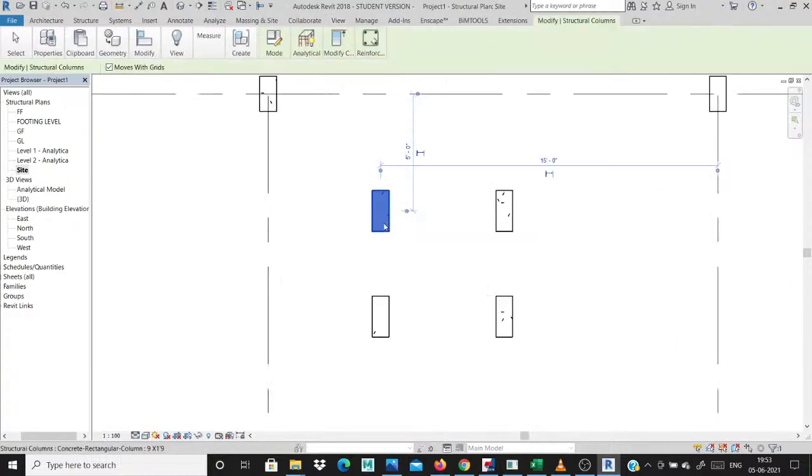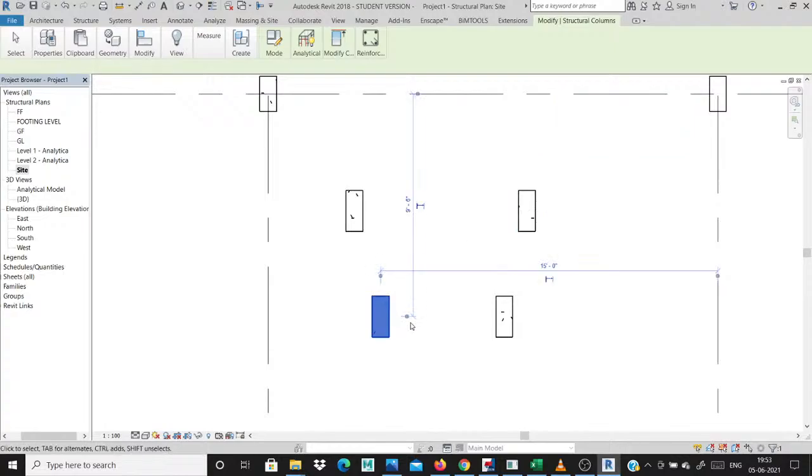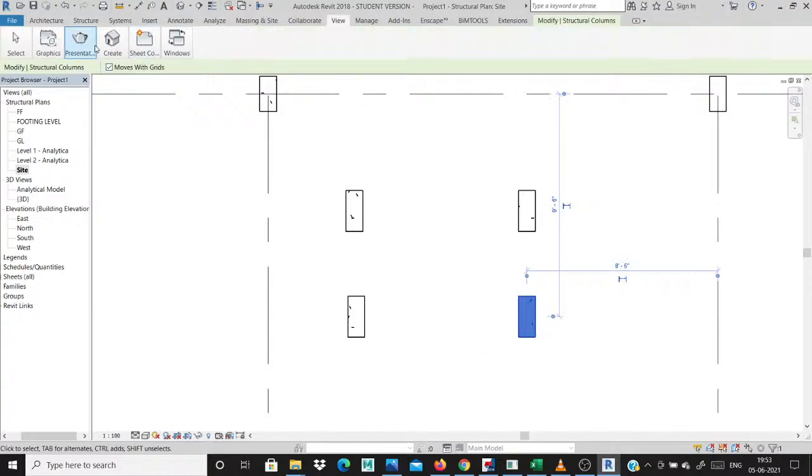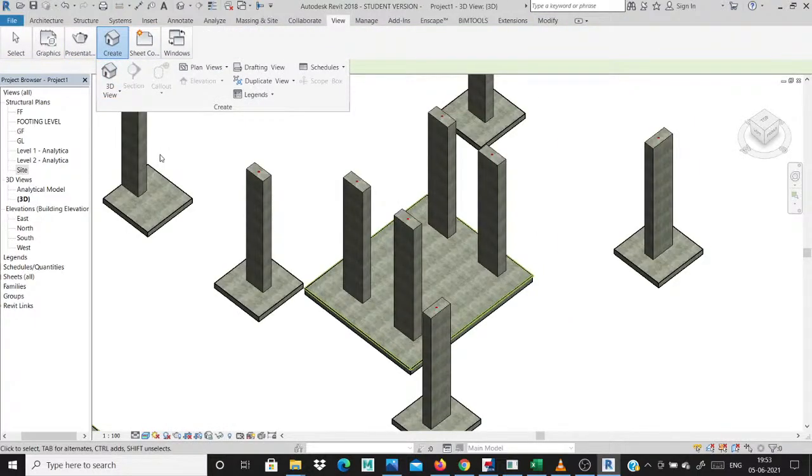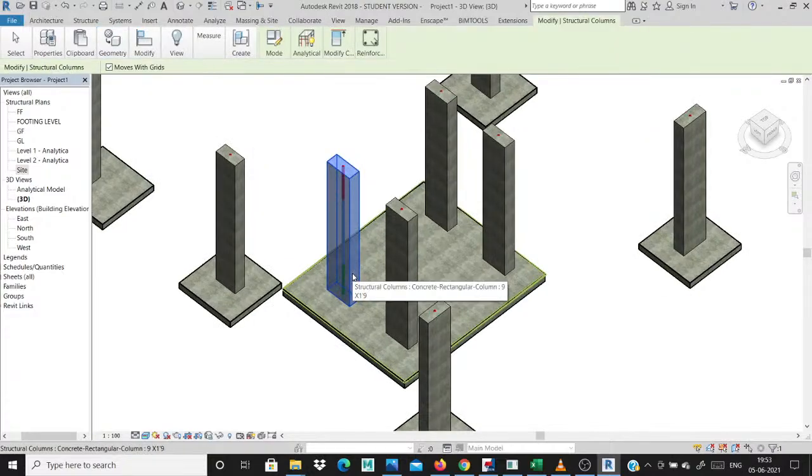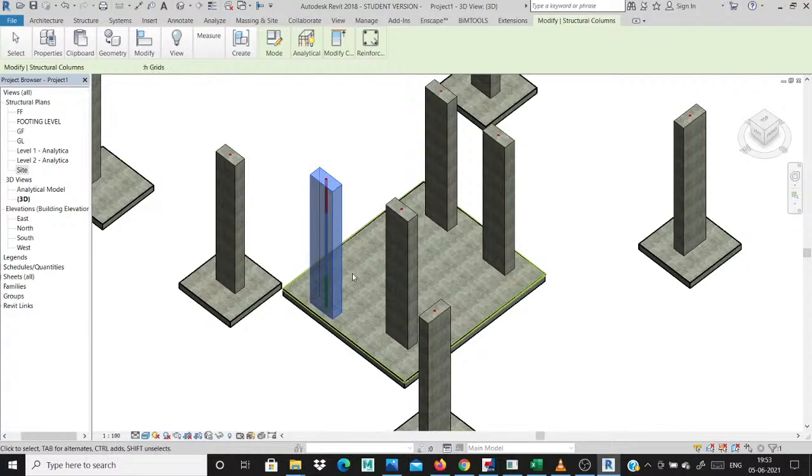Then how to create the shear wall for these areas. I move this column some distance, that's only to make it easy to understand. How to create the shear wall for these mat footings? You simply created the lift portion. The lift portion has four columns, and the four columns are converted into a mat. The four sides are provided with the shear wall also, right? The four sides are provided the shear wall. This is our lift area, right? This is our lift area.